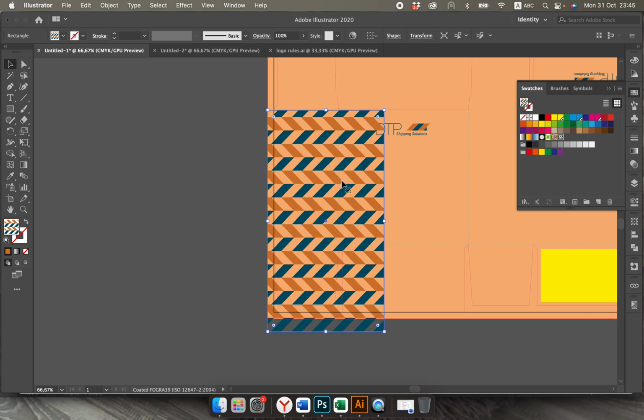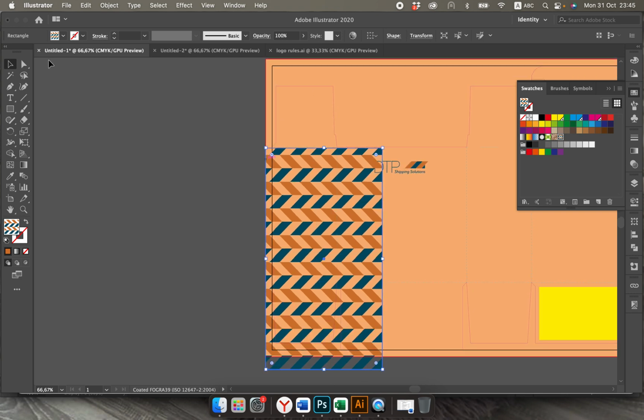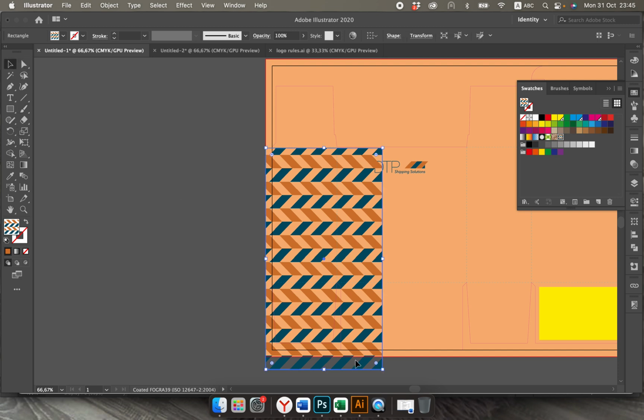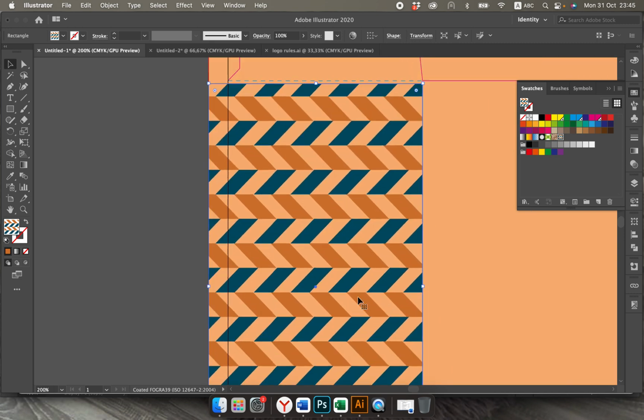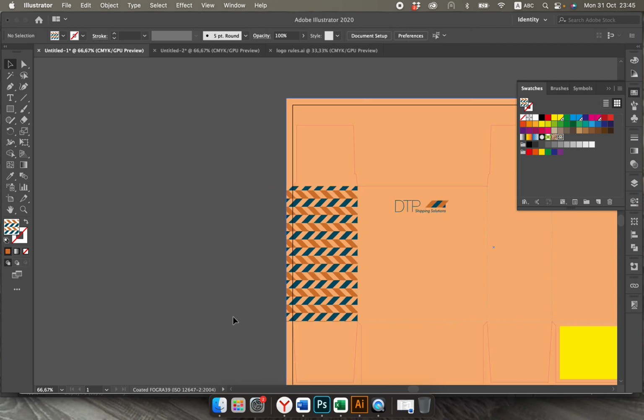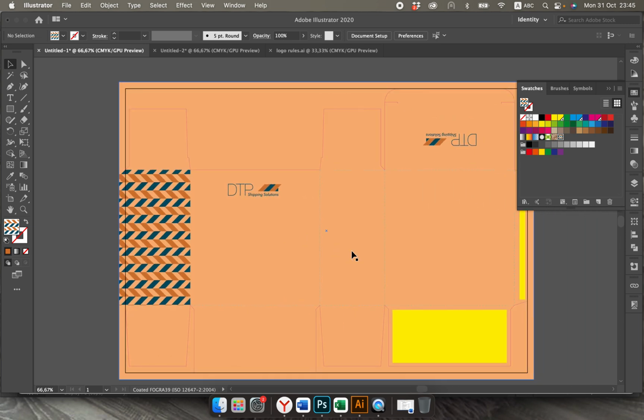And now one more thing, the rest is probably okay. Now I need to go to the scale tool, then fix my pattern inside of this frame, click OK, and now use shift again just to make exactly the same size of my package which I would like to make visible. Now you may see the pattern became smaller, because this is the way you could make the elements of the pattern inside bigger or smaller, and just change the frequency.